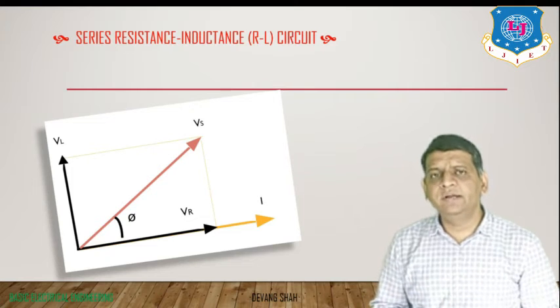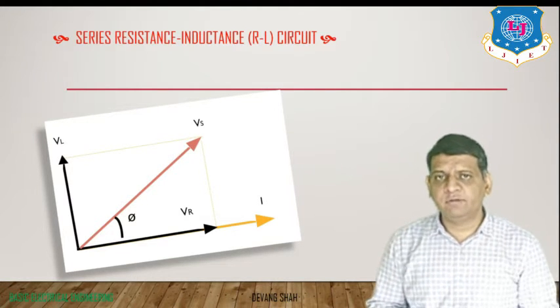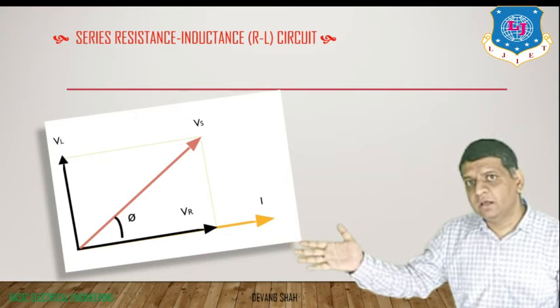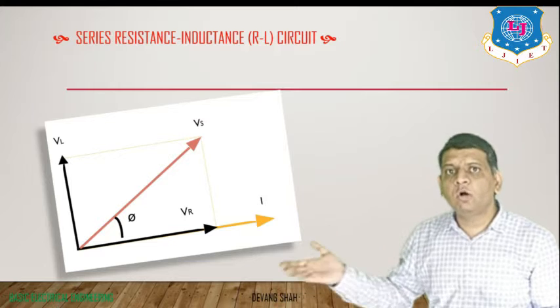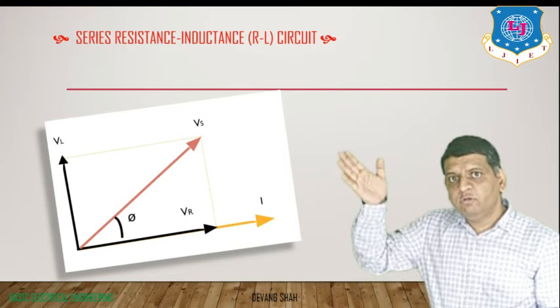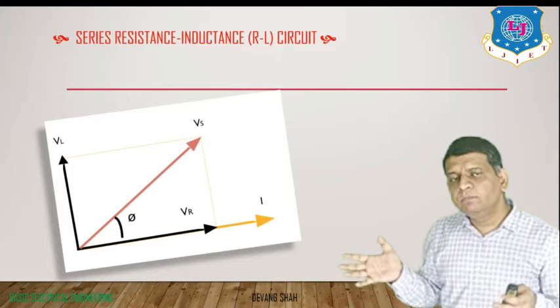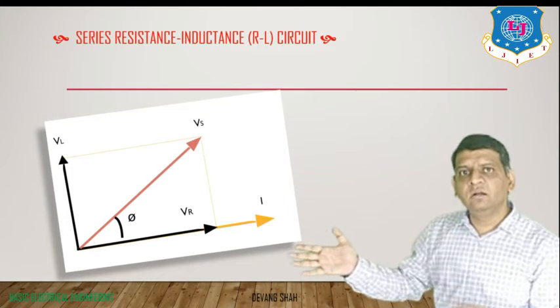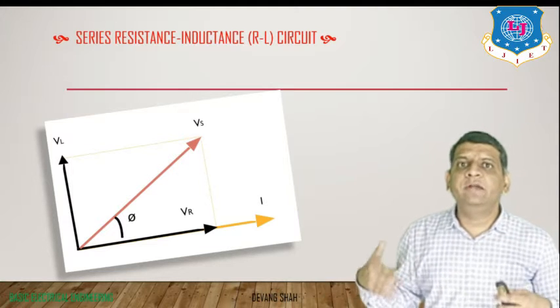Going into more detail with our phasor diagram, you can again observe the phasor diagram. From this you can straight away see the triangle, where the x-axis is defined as the voltage drop across the resistance, and the y-axis is the voltage drop across the inductor. Once you take this triangle, you will find the diagonal, which is your applied voltage V.